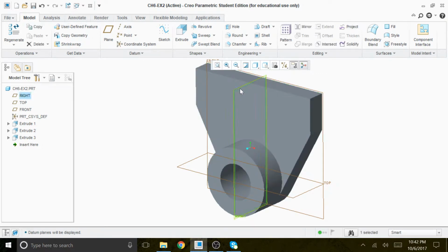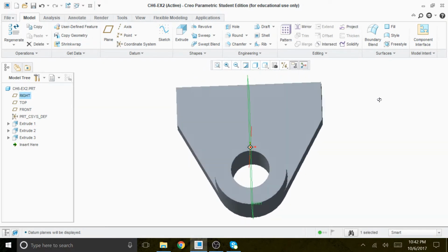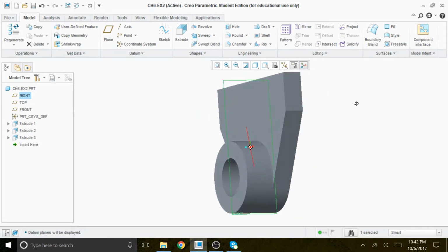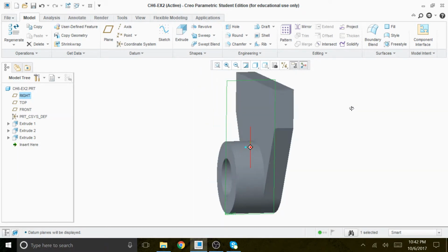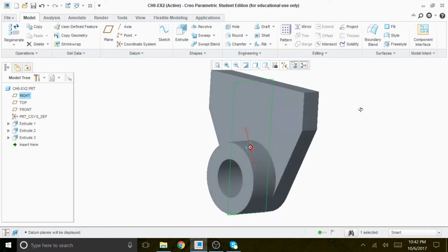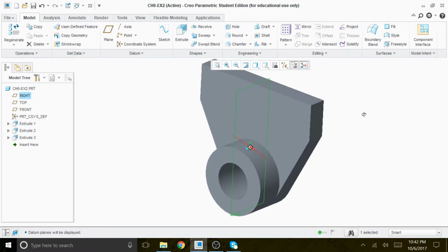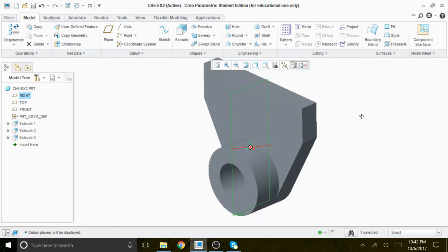So all right, you can see that you rotate them, and then you want to ensure that that plane is the one that we wanted to place the rib. Otherwise it's not going to work, okay? For a rib profile to work in CREO Parametric, you must use a plane. So if that plane is not there, you have to create a datum plane. Okay, let me do this.